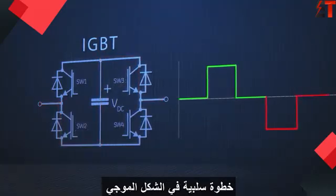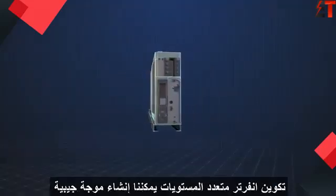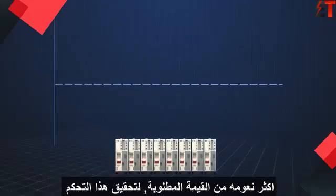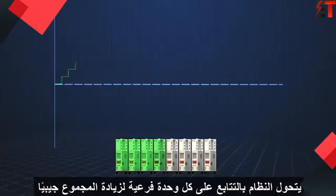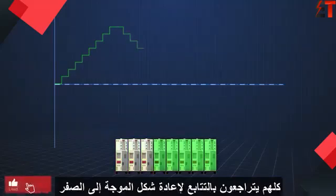Adding more submodules in what is called a modular multi-level converter configuration, we can generate a smoother sinusoidal waveform of the desired amplitude. To achieve this, the control system sequentially turns on each submodule to sinusoidally grow the total voltage of the converter in the positive half cycle until the peak. It then turns them all back off sequentially to bring the waveform back to zero.